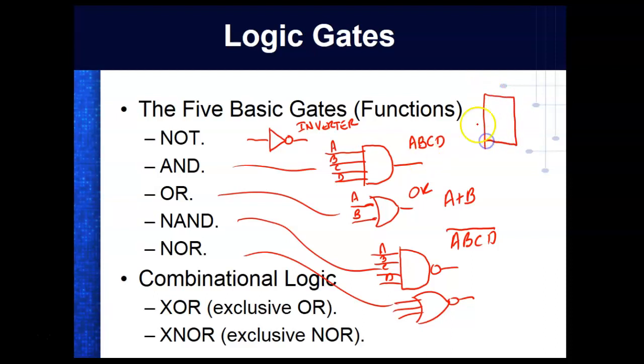And so this gate right here would look just like this. And then I'd come up here and I'd put the symbol for an AND. And that's the way you program. In an OR, I'd put a different symbol in there. So this is that language, function block programming. You program with gates, but you don't use the ANSI symbols.